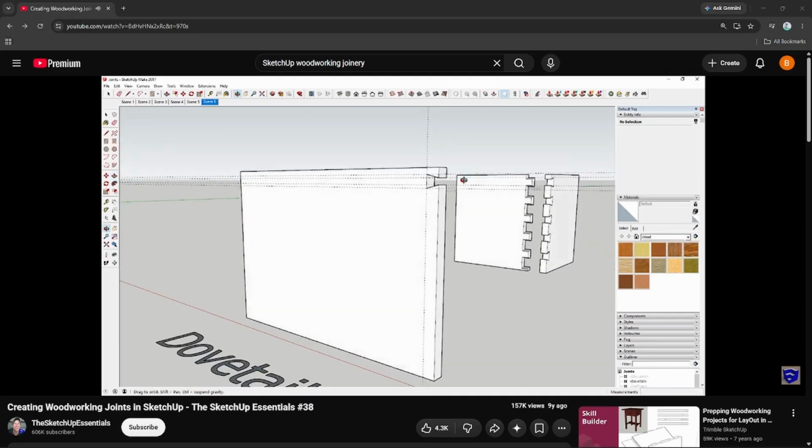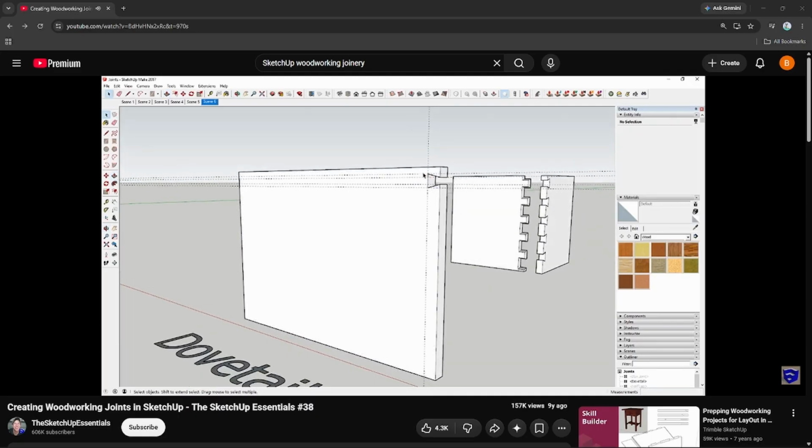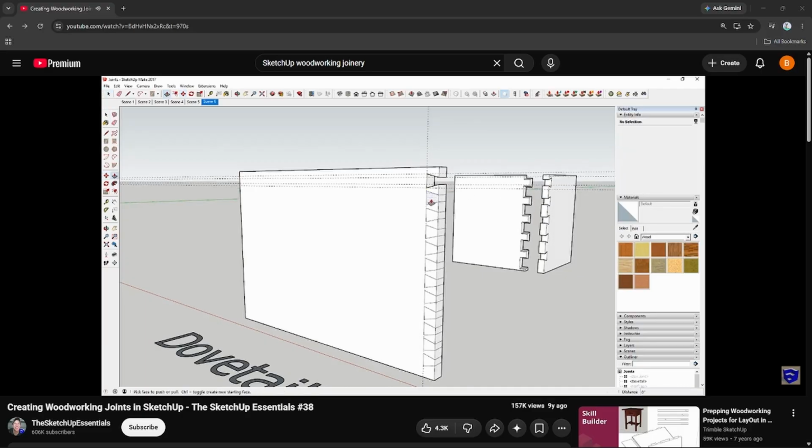And then the nice thing about doing this is now you could come in here and you can just select this geometry and you can use the move tool in copy mode to create copies of that geometry. So you could copy it once and then type in something like ×7 or ×10, something just like that. And then you can just push pull these pieces across.